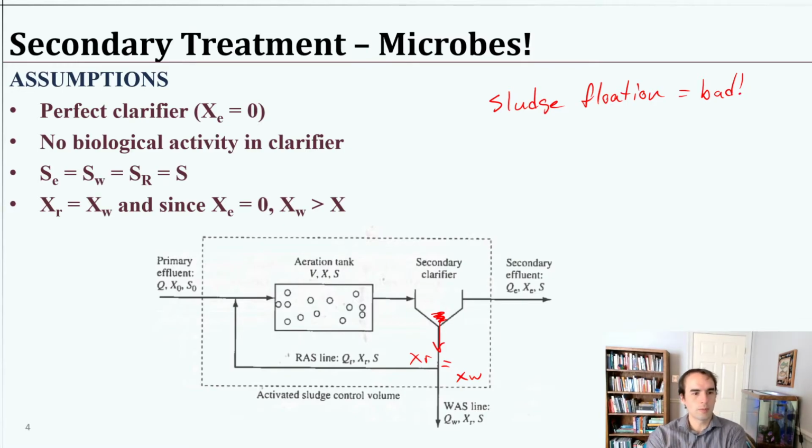And so treatment plant operators will try very hard to keep the sludge in a suitable state. If you grow the wrong type of bacteria, maybe your pH changes a lot and kills off some bacteria and the wrong stuff starts growing.